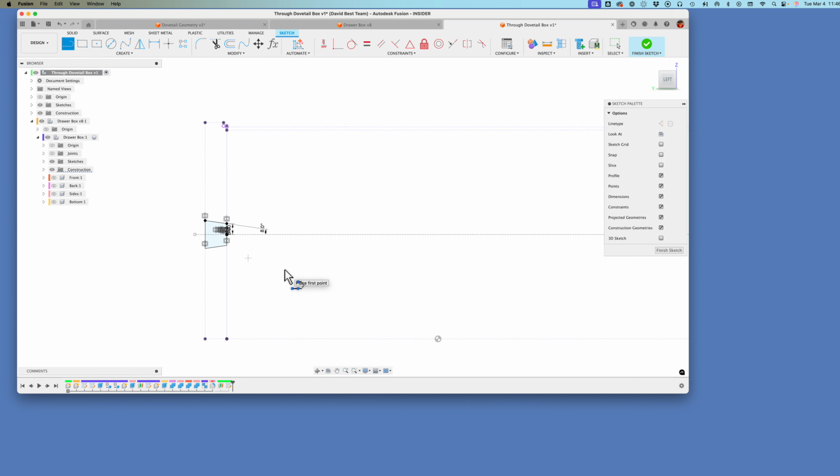All right, so we got one pin in the middle of the drawer side, and it's a total of 16 millimeters tall, and it's got an 8-degree incline there. Sometimes this is specified as a ratio rather than an angle, but I have cutting tools that will cut an 8-degree bevel on the saw for cutting pins and tails. So I generally use that. You know, make it whatever you want.